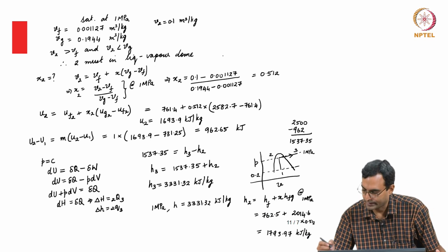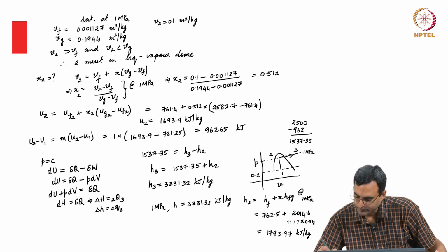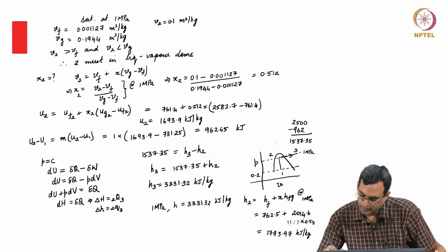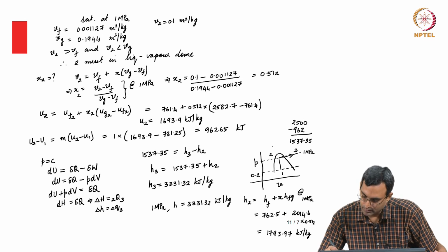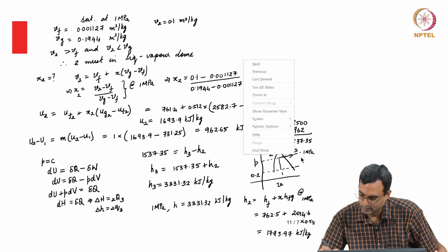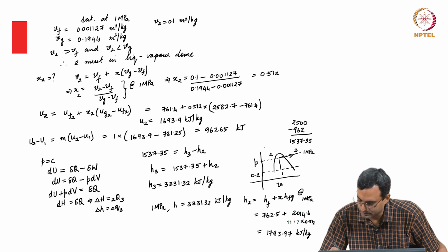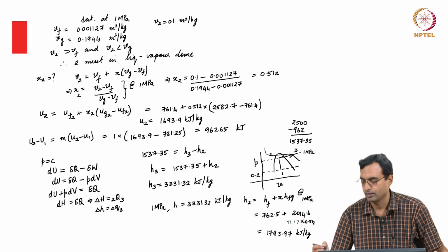So, I can indicate that here. On a PV diagram I have isotherms which go like this. I am now looking for an isotherm which cuts somewhere here. I am looking for a 430 degree isotherm which I know will cut somewhere here, and that is my point 3.